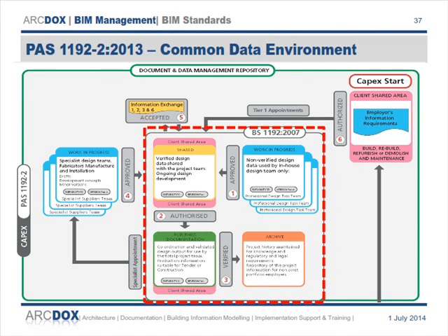And again, then once the shared information has been resolved, you can then publish that information. So the third and green box there is published information. And published information are the outputs from the model, the documents that you're going to produce, the drawing sheets and schedules and things that you're going to produce out of the model. Again, they have to be verified, they have to be authorized to go into a published location. But everybody should have access to that. And the last one is an archive, so planning stage, design, whatever, various stages along the project, tender stage, you can archive information into the archive location.